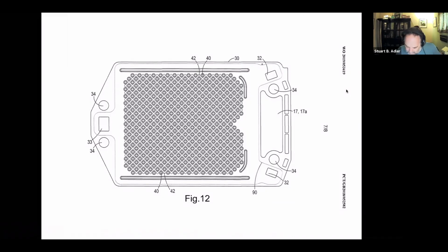Okay, so here's the fuel side. The way this particular cell is manufactured, the seal on the anode side is actually a weld. So they take the cell, which is made of stainless steel. The stainless steel part is on the anode side, and the whole cell sits on top of the stainless steel. So to make a seal, they just take the uncoated side of the stainless steel, which has all the holes in it, and they literally weld it to the interconnect plate. That's what this line is. So this line is the weld. And that seals off the air, creates a continuous fuel compartment.